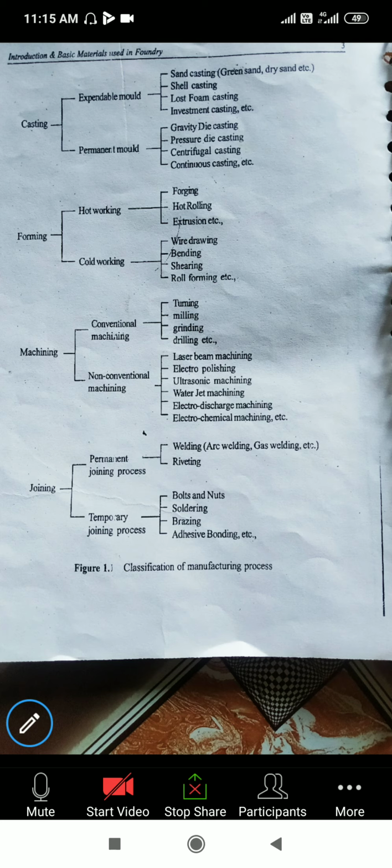Okay, in hot working, the hard material is allowed to change its property above the recrystallization temperature, so the property of the hard material changes and it can work in a hot working condition. In cold working, if the material is brittle, you cannot follow the cold working condition in the forming way. Okay, so these are the simple forming methods.